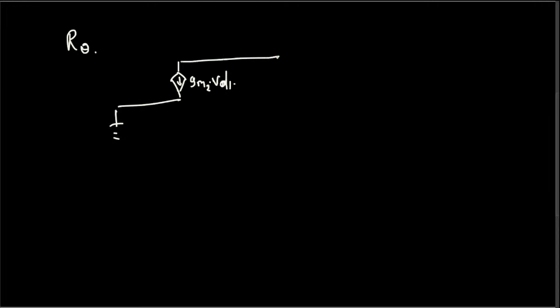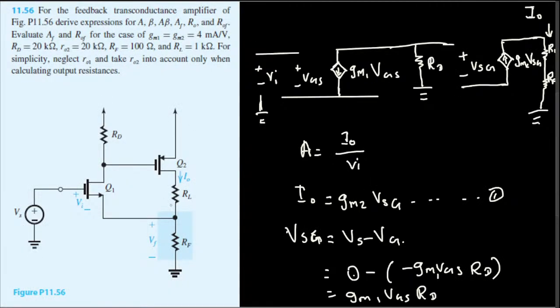We're just looking at the PMOS. So there will be the RO2 output resistance, and that is parallel with the feedback resistance, which is RF. We open circuit the RL, so RL is gone, RF is there, and there's output resistance RO2, that is only visible when we draw the small signal equivalent model, so that will be there.